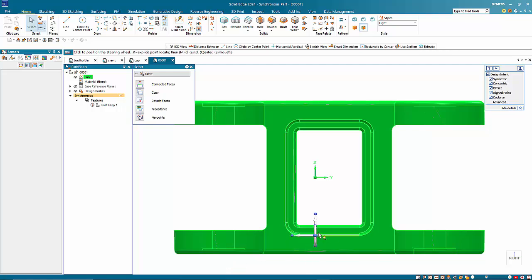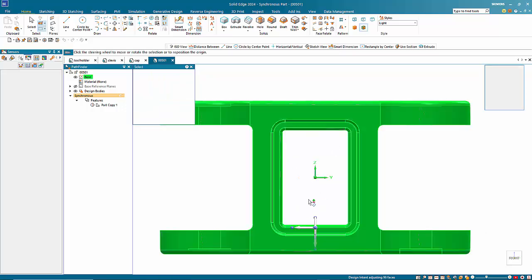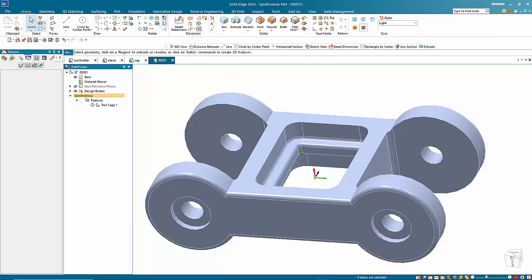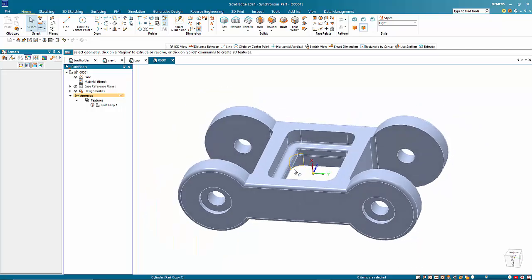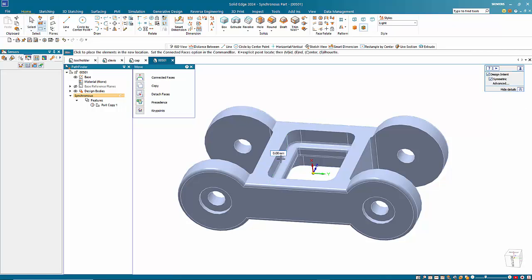So if I position my steering wheel on the midpoint here and then drag it across in that direction, I can click up on that coordinate system, and then that makes it all symmetric. So now if I pick up off one of these faces here and adjust that through, you now see that it's automatically picked up on symmetry, which we could obviously turn off if we wanted.